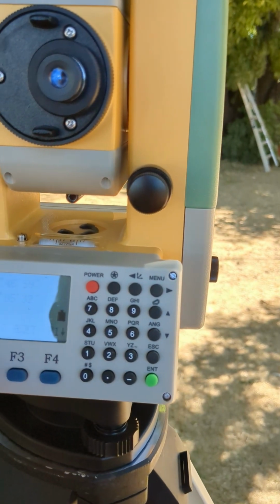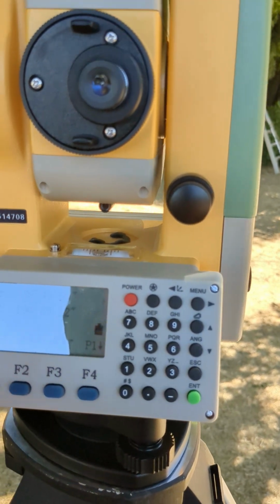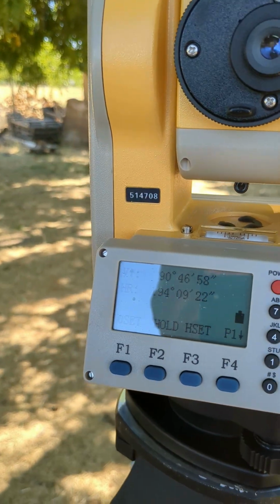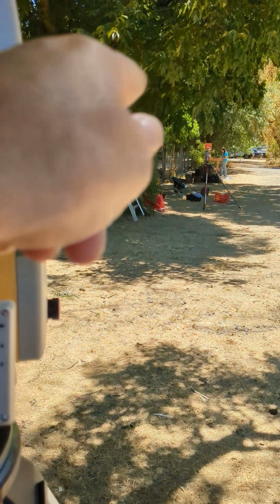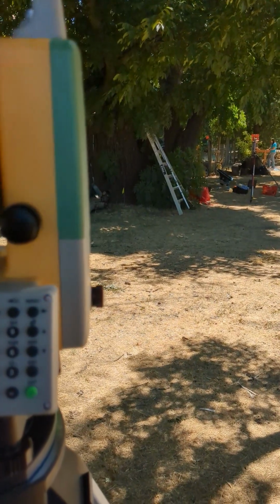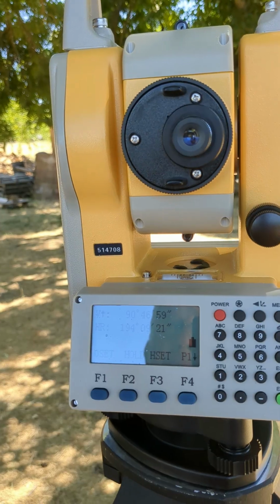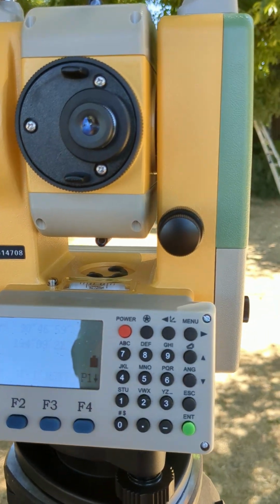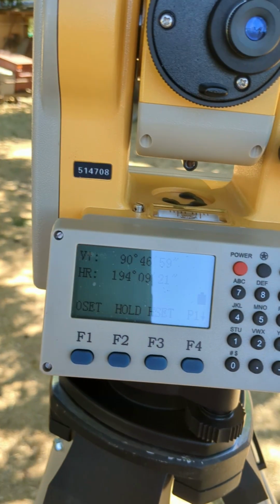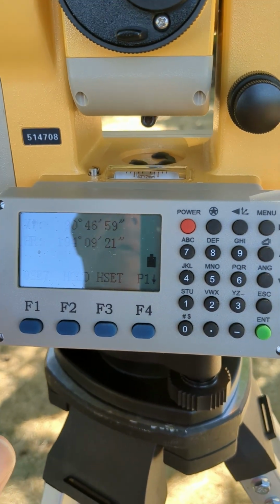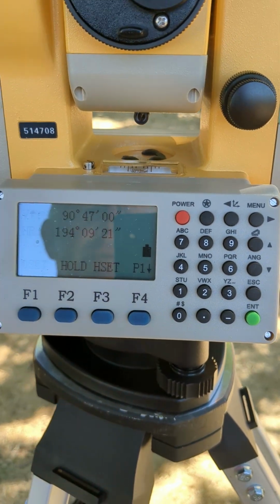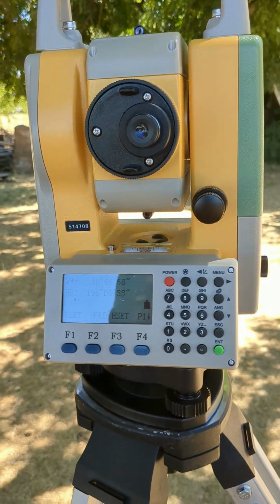But what we don't want to do is use a compass here and get another north setting. We have a spot we know about, that spot over there, and we're going to backsight that spot to here instead of putting a compass up here and measuring another north. That would just cascade error by having to make new measurements each time. So let me take it to the next step here.